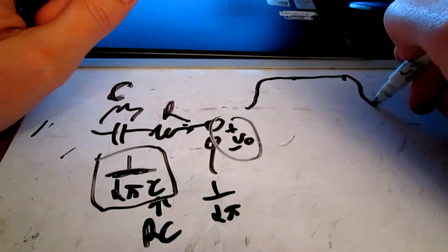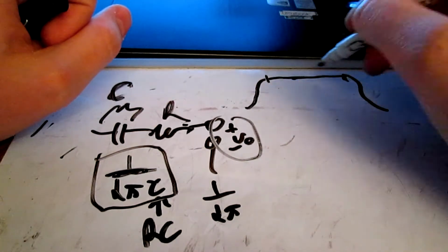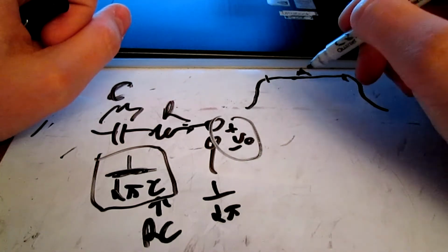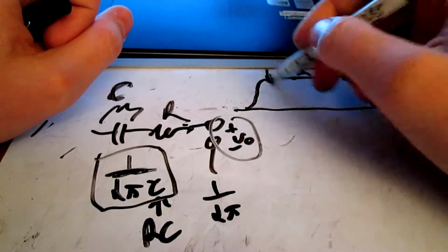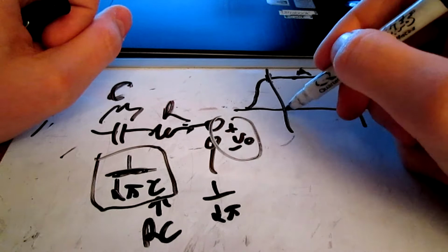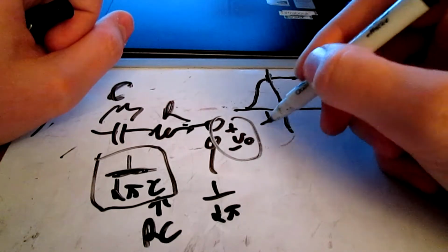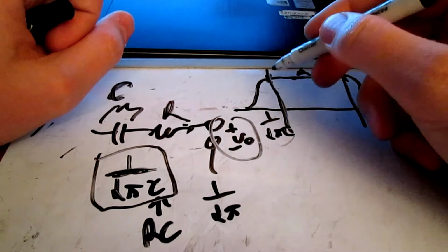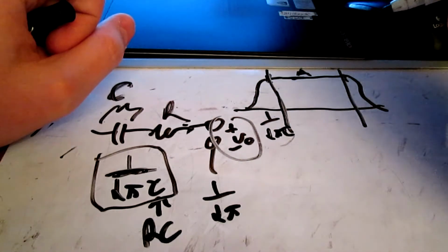So this is a typical Bode plot. This is our gain, our mid-band gain. Here is our lower 3 dB. So this will be 1/2 pi tau. So that's 3 dBs from our mid-band gain.